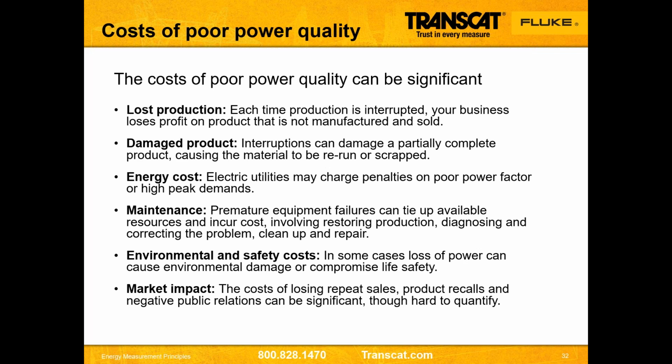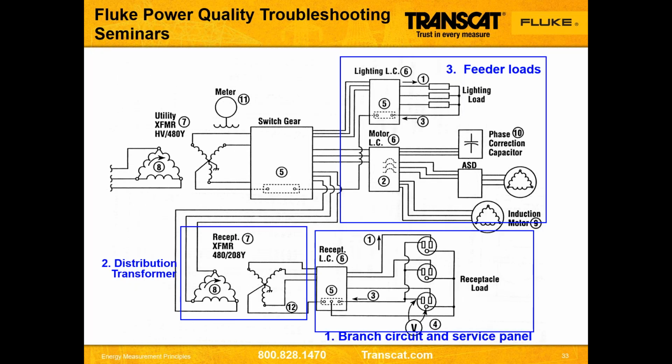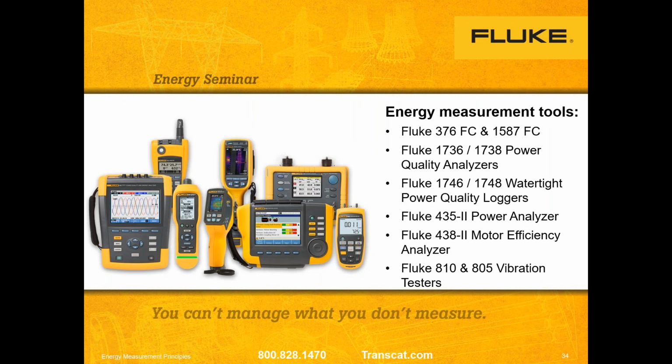So the quantity piece and the quality piece are actually being done at the same time in these power analyzers. Majority of them, if not all, will do some form of this, but actually allow you to do both quality measurements and quantity measurements at the same time while I'm doing my surveys. And we want to, again, move around the plant. So branch circuits, distribution, looking at electromechanical loads off the feeder circuits, figure out who's using all this energy. Give you kind of a flavor for the electrical side.